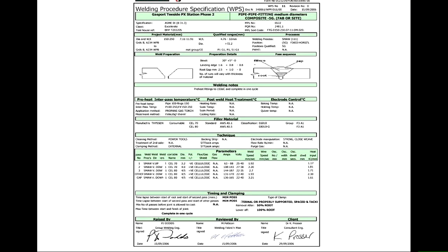And what you're doing as a welding engineer is trying to keep the welders to this preparation. So the guys that were standing beside, who may well have been the engineers, not only are there for safety, they're also to make sure that the welders are not suddenly welding too quickly or doing something like that. They check the settings on the power supply. Modern power supplies that are digital, you can say, this is welding procedure number 11. See this one here? So you have actually a button on the power supply which says procedure number 11, and it automatically goes to the settings that you require for that.